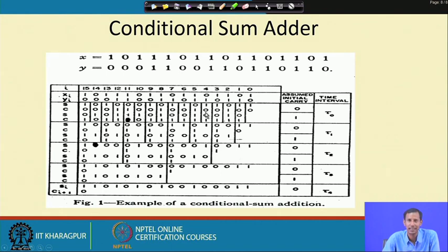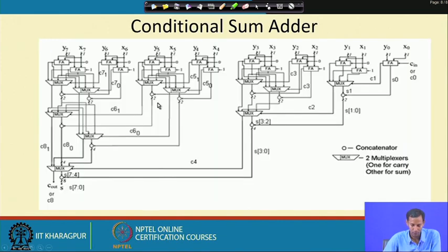Then again this will affect what? The 5 position. So, in the 5 position what are they? 1 1 means 0 and 1, 1 and 1. So, that means considering the carry input bit of 1, that is 1 1 1, and considering the carry input bit of 0, that is 0 1. Okay. So, now based on this, for carry input bit of 0, what will I choose? That is 0 1. For considering the carry output of this particular stage 1, we will choose 1 1 over here. Okay. So, then again you just come to this point.